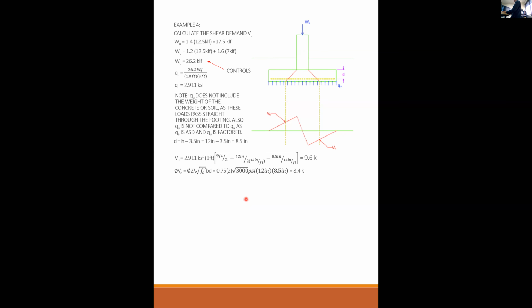That's right. I know it's trivial, but that's the check. That's why I keep harping on you guys. Check: phi MN greater than MU. Phi VC greater than VU. It's not in this case. It's less than VU. It's no good. Why is it no good? Well, remember, I guessed at 12 inches in the first place. That was just a total guess. So let's try again. Let's guess 16 inches.